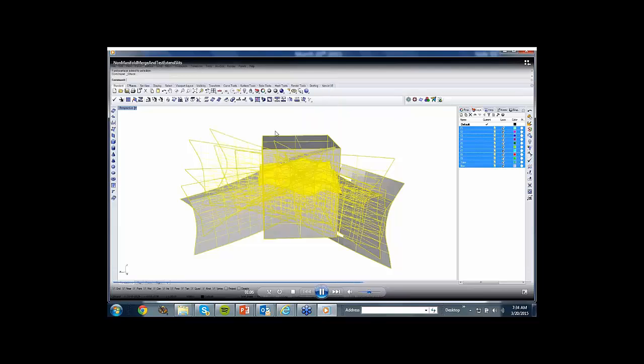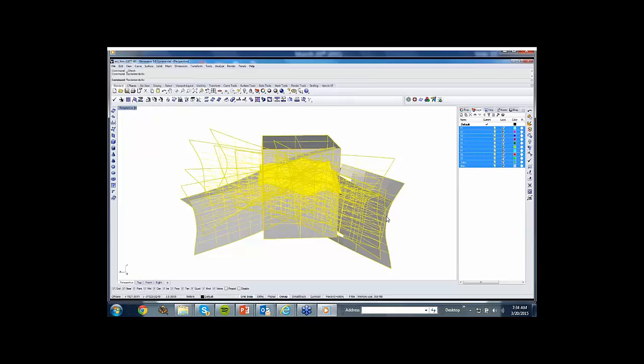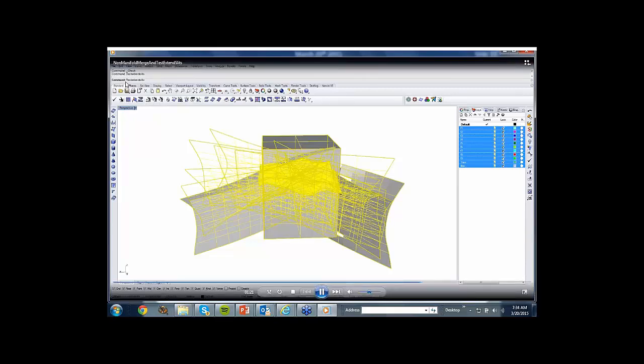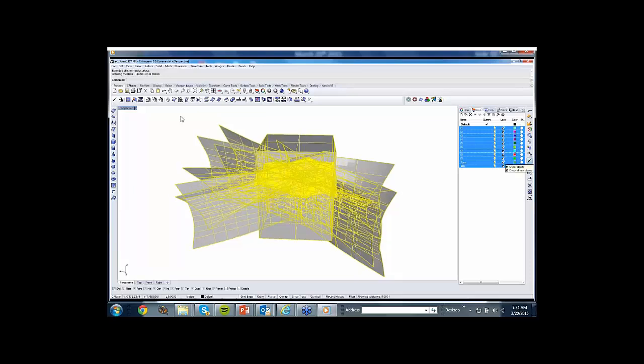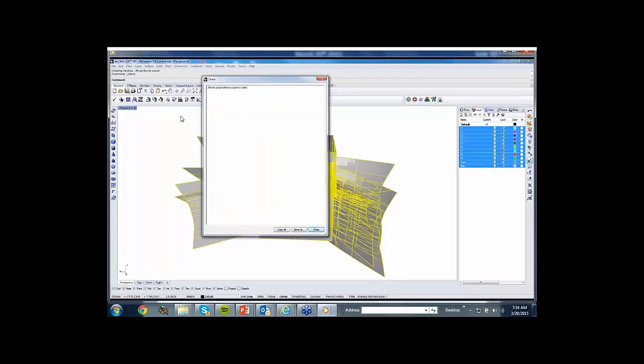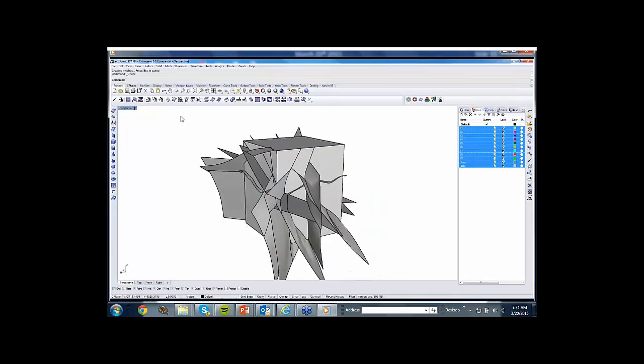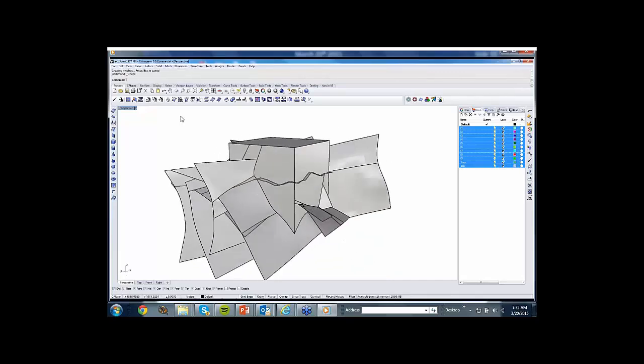This is a telltale sign that this is bad geometry. If I do a check, it says this surface is not valid. And the reason it's not valid has to do with the fact that some of these surfaces have been cut, not all the way through, so topologically they cannot be represented properly. So I use this command called test extend slits, which has been made for us, for Itasca, and which will be part of the complete offering of the Rhino people. But now we have an object that we have created, except it has wings, that is valid. So this is one single non-manifold polysurface that is valid.